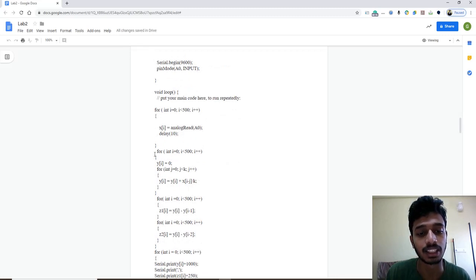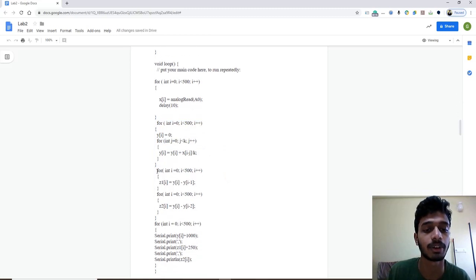What we do in difference filters is, our basic operation here is to find the peaks. Peak detection is our objective here. As the original data has some noise in it, initially we smoothen it using a moving average filter. My order is 8 here as usual. This will be followed by implementing difference filters.